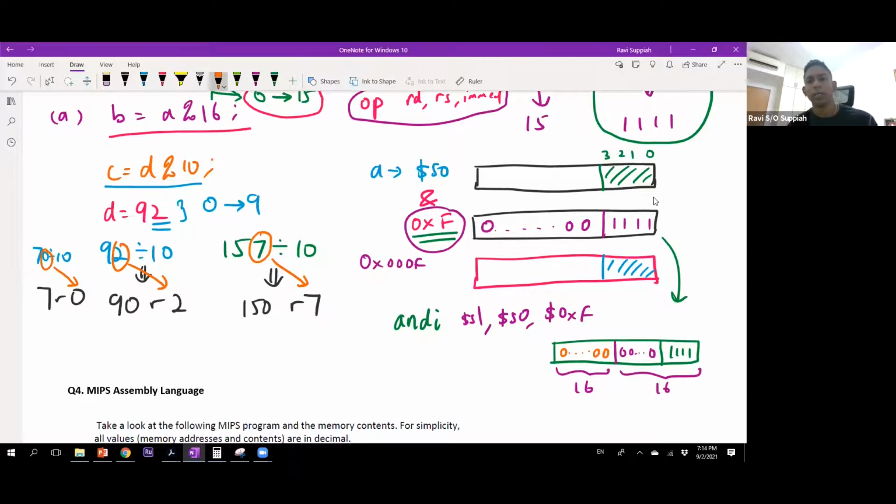We will be looking more into the behavior of the processor and how this extension comes into play when we are looking at the data path and control chapters later on. But this gives you an idea what is happening when you write an instruction. When you write an instruction, you are telling the processor to carry out some activity, but the processor still needs to interpret the instruction correctly. That is where the instruction format comes into play. We will be looking at this again in the next chapter when we're looking at the encoding part.